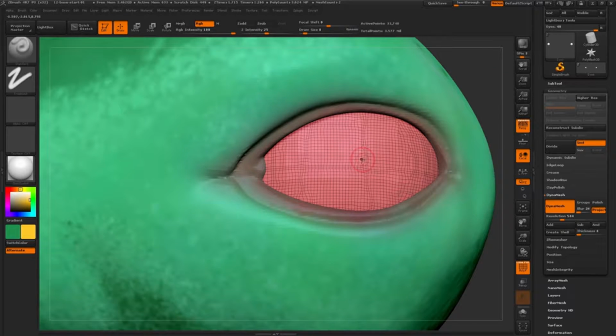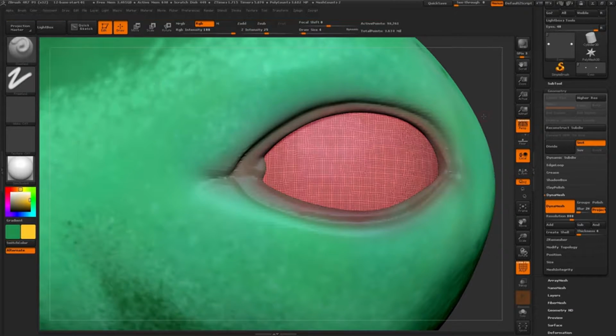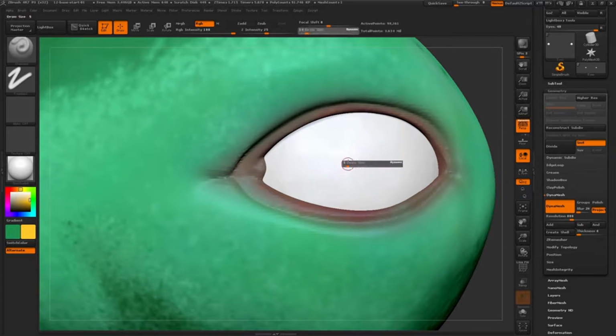Continue to adjust the resolution until you get the paint resolution that you need, and be sure to disable the Z-Add feature for the Smooth brush if you wish to continue smoothing the surfaces for PolyPaint without smoothing the sculpture details later in this process. After reapplying the PolyPaint again, this resolution is now giving me nice PolyPaint details.